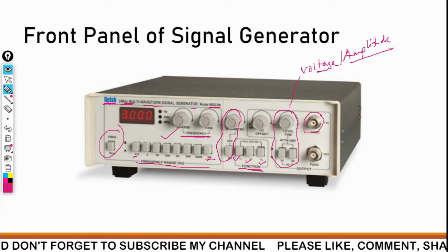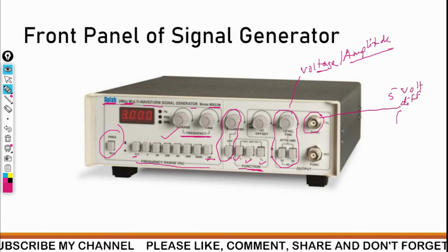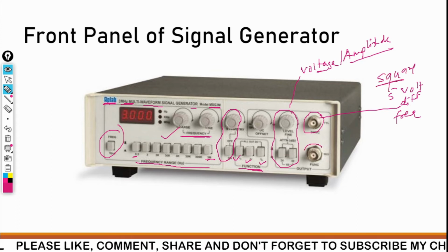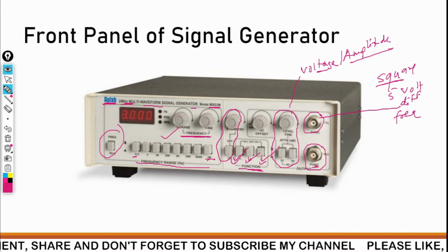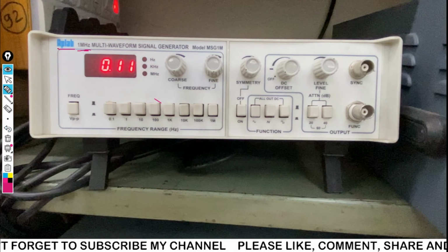This is the TTL output, where we are going to get a 5-volt constant output with different frequency. So we are going to get a square waveform from this particular TTL output, while from this one we get the functions. Functions may be sine, triangular, square, with different voltage and different frequency. This is the 1 megahertz multi waveform signal generator.